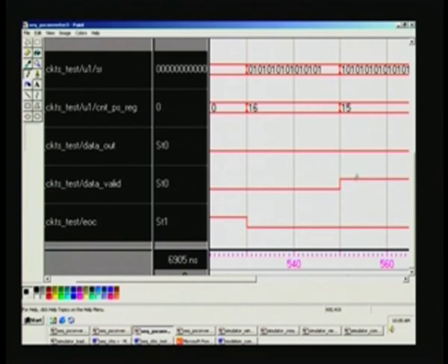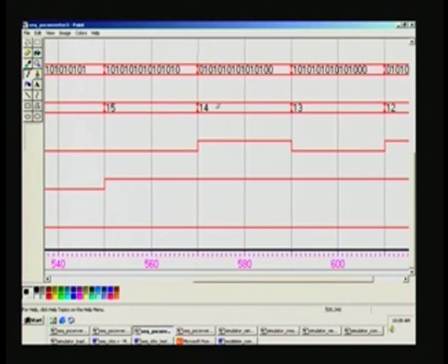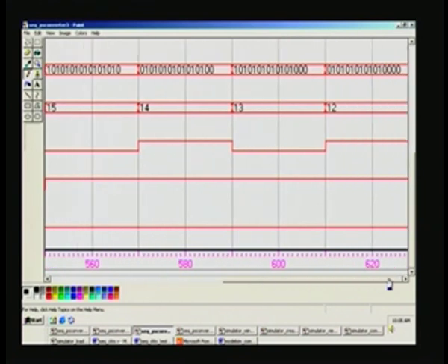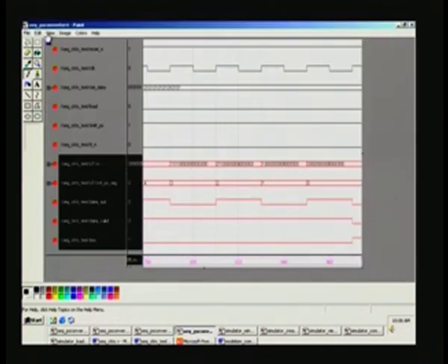So, 0 is there and data valid is asserted here, and count keeps on decreasing, and you can once again see 0 1 0 1 again, same bit pattern, and it keeps going. So, finally, we will have one more waveform where you see the end of this left shift.